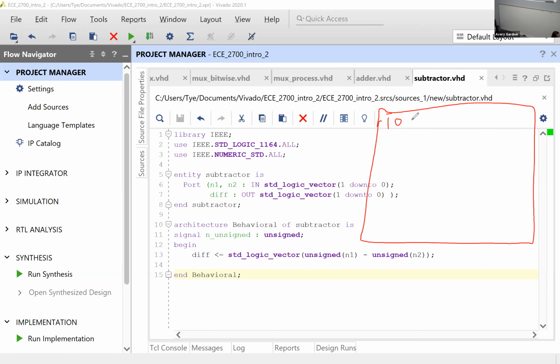a top file. I've built a mux. I've built an adder, subtractor. They're connected to the mux. And depending what select is doing, we're either going to put the output C as the addition or the subtraction.